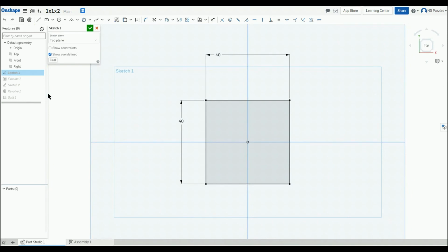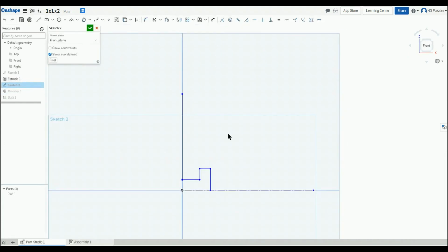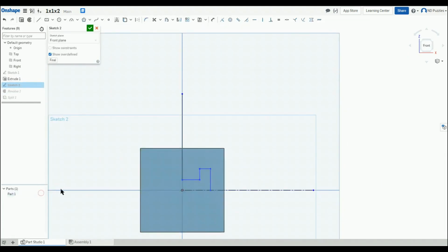All you have to do now is to use the cutting tool to cut the body using this surface, just like I'm showing you right now. Choose the body and the surface just like you are asked to and hit OK. Then you will have a fully functional 1x1x2. To see the mechanism, just hide one of the pieces and you will see the hook.